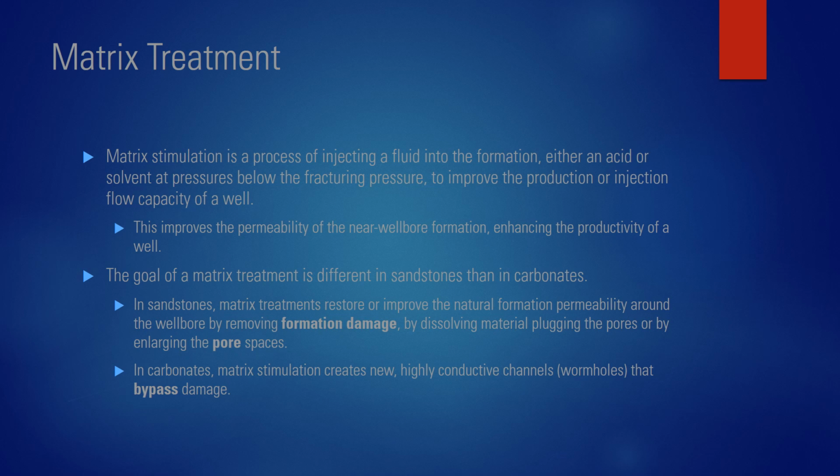In sandstones, matrix treatments restore or improve the natural formation permeability around the wellbore by removing formation damage, by dissolving material plugging the pores, or by enlarging the pore spaces. In carbonates, matrix stimulation creates new, highly conductive channels, called wormholes, that bypass damage.